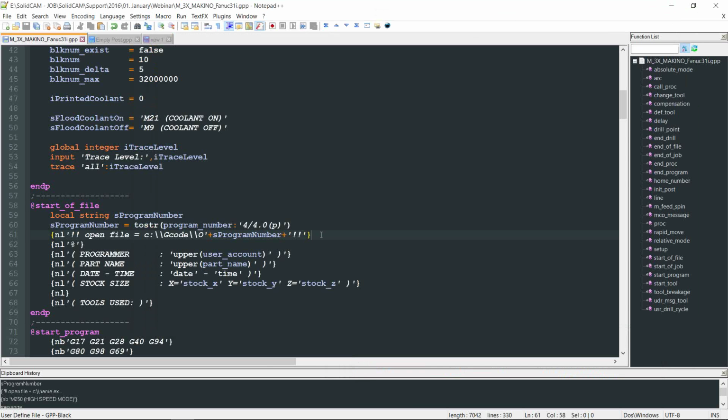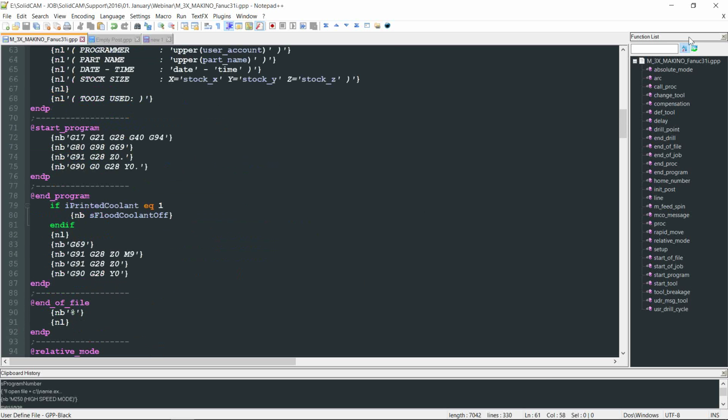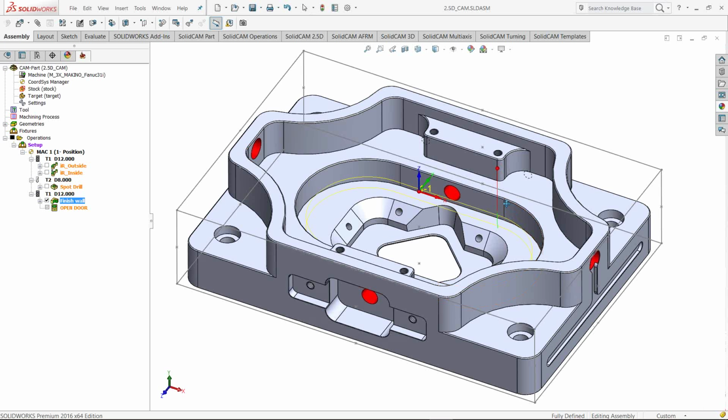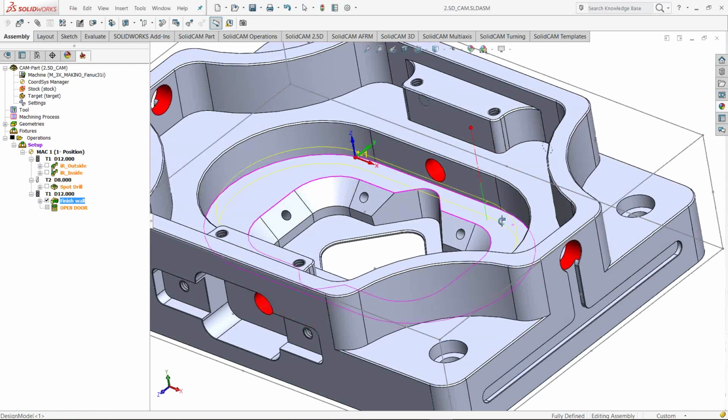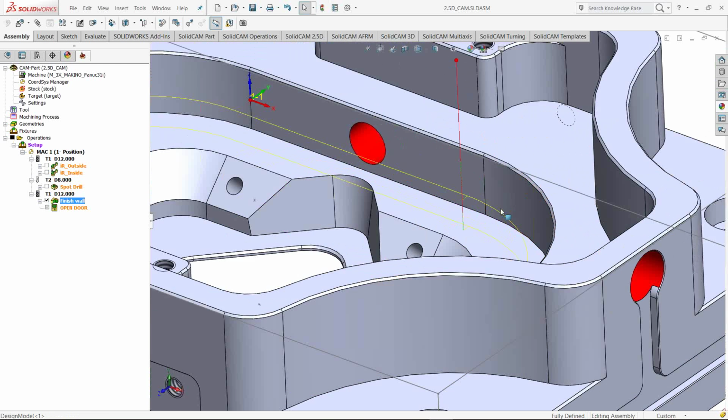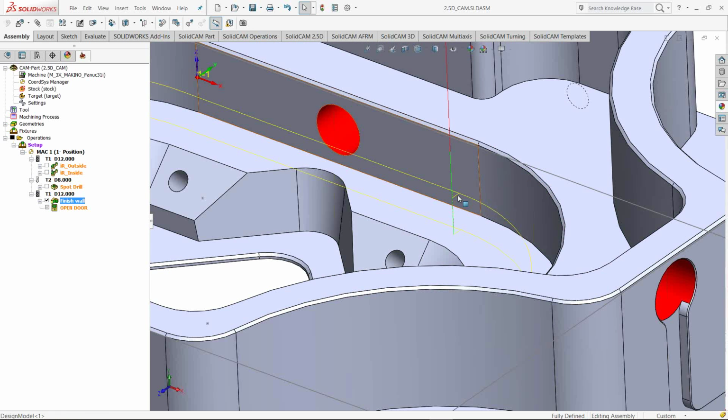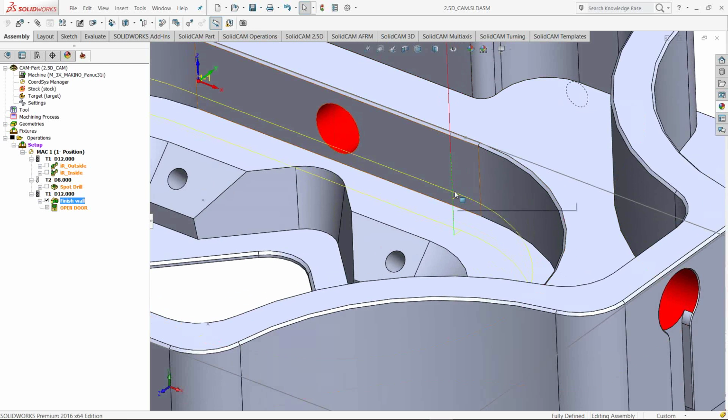And the second one is, I will delete this one, or no, I will still leave it. But I would like to show you another example, and I will finish with this webinar. The finish wall, as you can see here, I will just jump into a little bit of the analysis of the toolpath. So what we have here is, the tool is going down, finishing the first pass, and then it goes out, goes to the second pass, and runs that again.